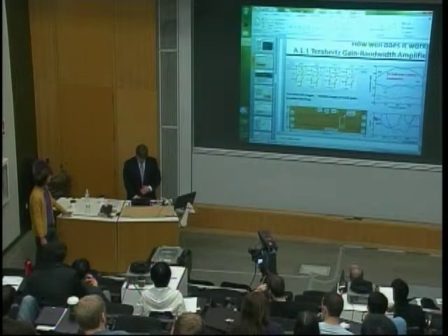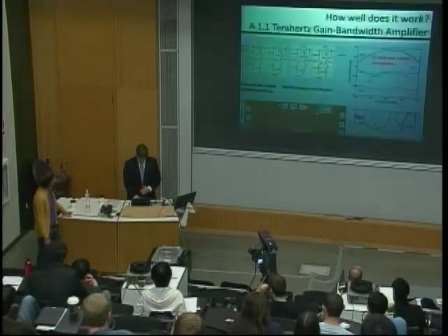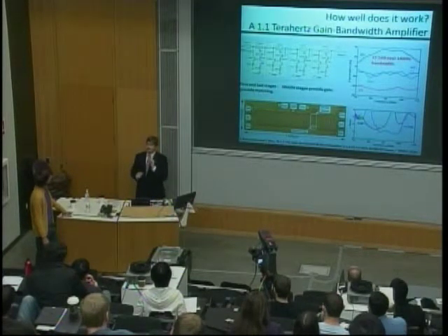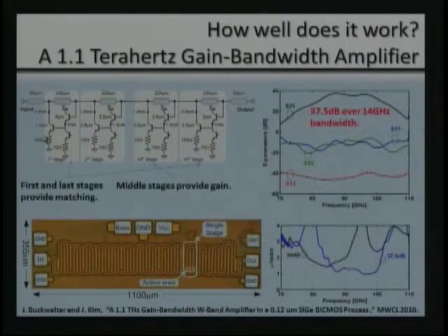It's an excellent question. I may have glossed over this. While we have positive feedback in each amplifier, we can introduce negative feedback in the feedback amplifier itself, through an emitter degeneration resistor. We taped this chip out back in 2008, and it came back and it worked the first time.